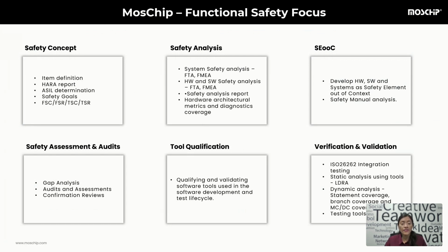Next comes safety analysis, where we run system level FTA and FMEA, analyze both hardware and software safety mechanisms, and calculate architectural metrics and diagnostic coverage. In parallel, we support SEooC development, enabling hardware and software to be reused safely across platforms with a detailed safety manual. We then focus on verification and validation using static and dynamic analysis tools like LDRA and performing integration testing with full coverage for MCDC and statement level requirements.